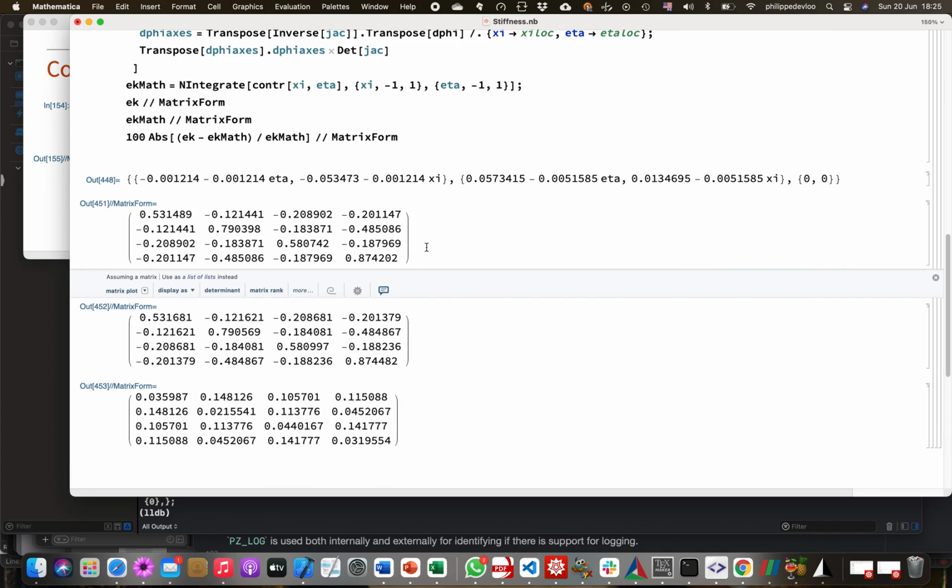The error due to numerical integration will influence the final result, but the error will be such that it does not affect the convergence rate of our computations. So it's good to know that our numerical integration is an approximate integration, but the fact that it has 0.2% of error is not something that we should be worried about too much. Okay, that's it.